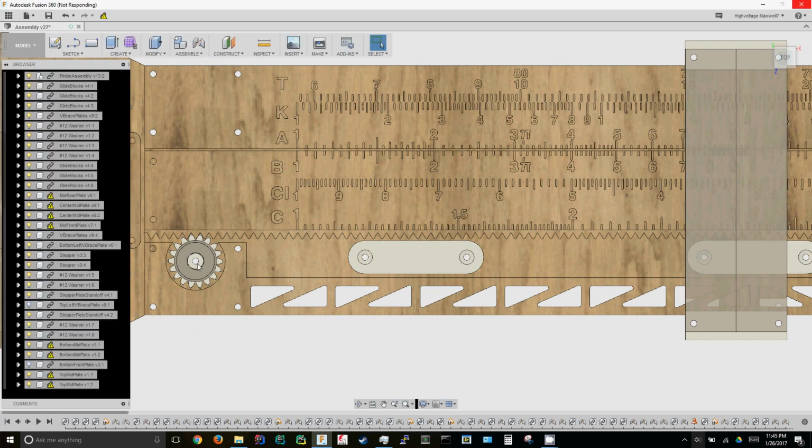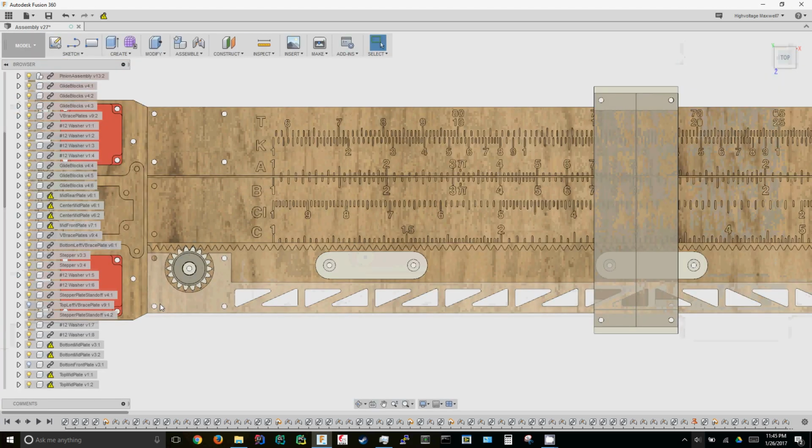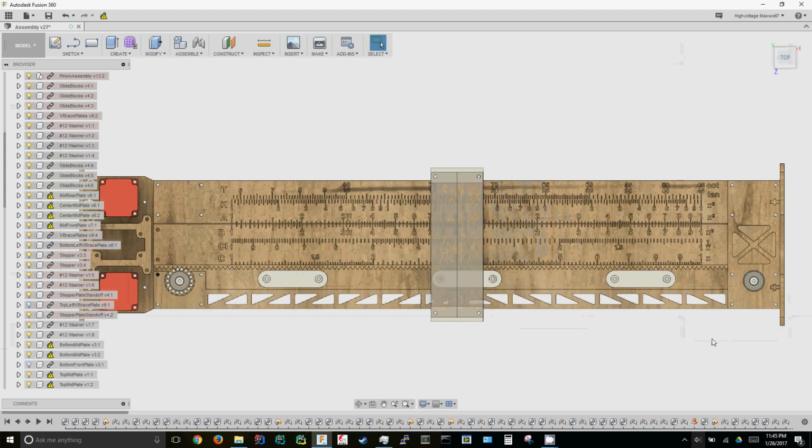This is important because there's one at either end, and as this thing needs to travel, there would be easier ways to make this middle slider move back and forth, but a lot of them are limited to one full slide length worth of travel, and I want more than that. I shouldn't say slightly, but like 50% more than that or so.